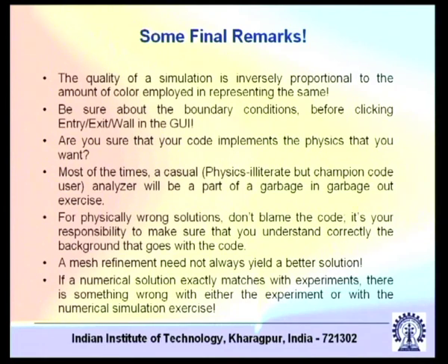But joking apart, if we take it very seriously, many times we are not very careful about the authenticity of the results once we get nice plots, and this is something which is very deterring. One should be very careful about what? One should be very careful about the physics that has gone into the CFD code. Once you consider the physics, one of the important considerations is the boundary condition. Be sure about the boundary conditions before clicking entry, exit, wall in the GUI, or inflow, outflow, wall.